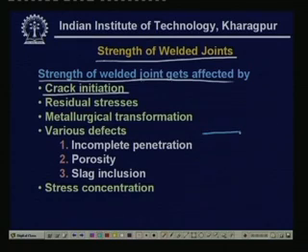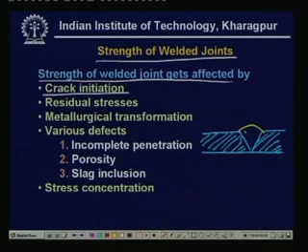One is that if you look closely into the welding process, then you see that here this is the metal, now welding is applied there, weld material is applied there. So here there is a zone which is in liquid state, right, and this is the melted portion of this metal. Then there may be a part which is adjacent, which is not melted, but which is affected by the heat applied in the main heat source. So this is called the heat affected zone.